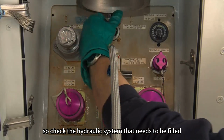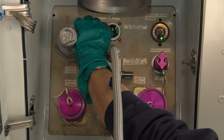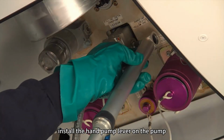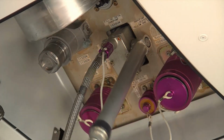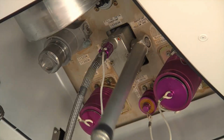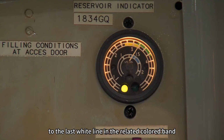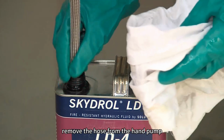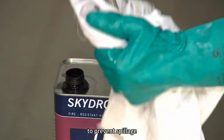Select the hydraulic system that needs to be filled. The selection is confirmed by a colored LED on the indication panel. Install the hand pump lever on the pump and start the filling operation. Fill the system reservoir to the last white line in the related colored band and not to the end of the scale. Put the selector back to neutral. Remove the hose from the hand pump and clean and dry the hose and its connections to prevent spillage.